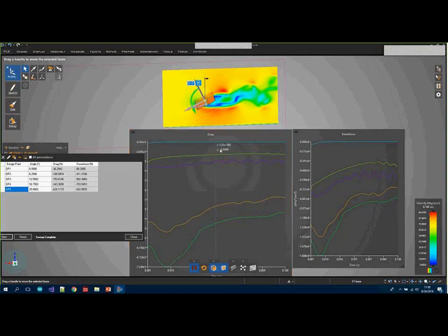So here are our results. We can see the plots. Everything looks good. Right? We can find here that probably the best option is 12.5 degrees or somewhere in between there. Right? From 6.25, the drag increased by maybe a little bit less than a factor of 3, but the downforce increased roughly a factor of 4 plus, nearly 5.